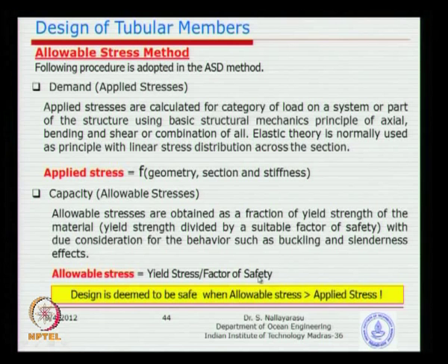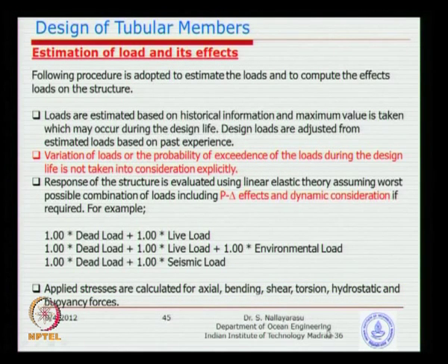But of course, the building still remains a little bit safe, because the safety that we apply here, we still use only a fraction of yield, and also after yield we have a so-called post-elastic capacity. That is why even if these norms are violated, you will see that none of the buildings actually collapse just because somebody has loaded slightly higher. But of course, in recent times you will see, in several places, instead of 2 stories you build 4 stories, then definitely the building is going to collapse.